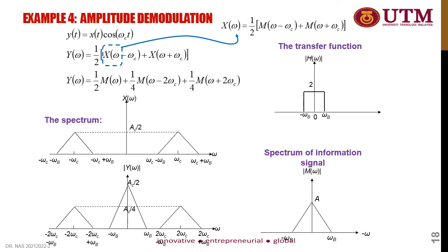In terms of mathematical representation, this is at the receiving end in the demodulation process. The signal x(t) is multiplied with the carrier signal. When you do the Fourier transform, you will get two components in positive and negative frequencies, while the amplitude is cut into half.